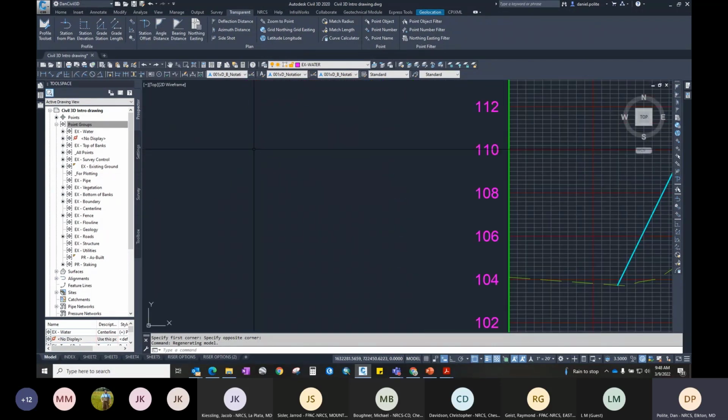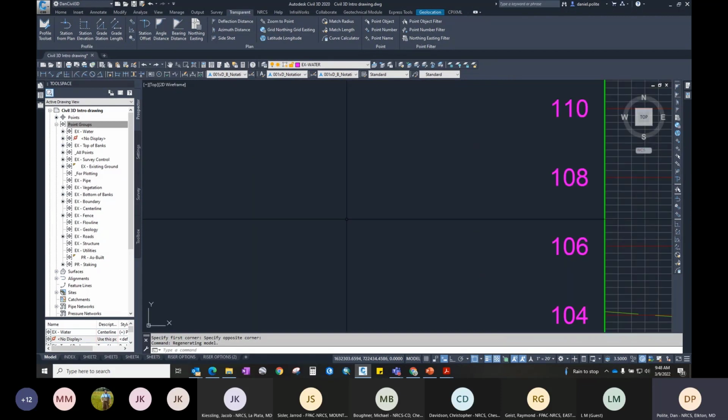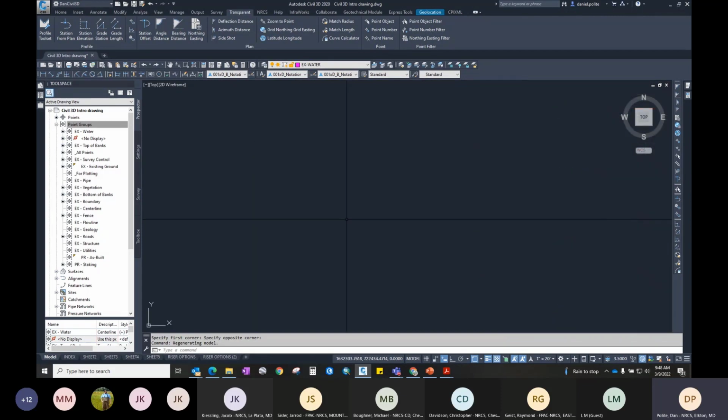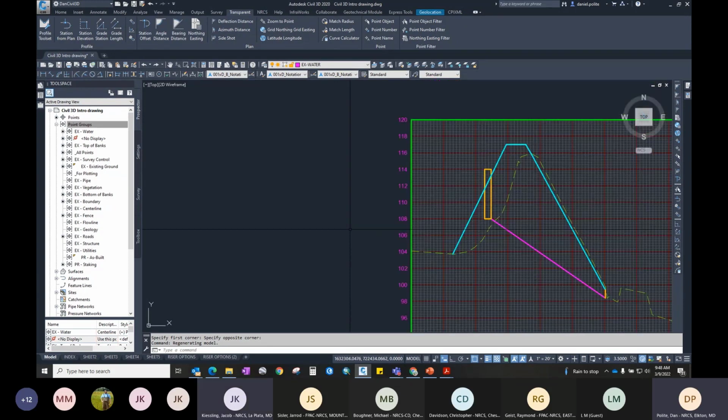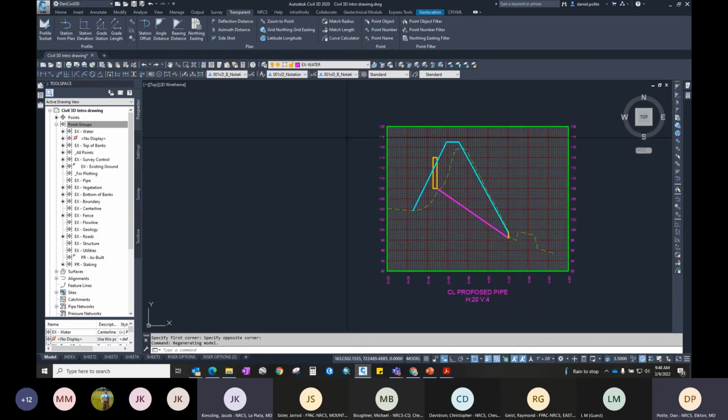Now, I will tell you with GIS, it's just the opposite. When you push the mouse button away from you, you're zooming out. That's an easy fix on GIS. Just hit options and then ArcMap options and then click the other box, mouse scroll in. Yep. Out of the box, it's just the opposite of what we do with Civil 3D. But yes, you can fix it.